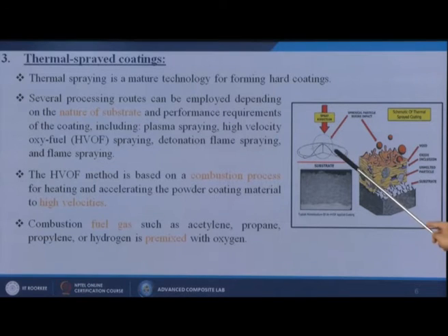Here we have the substrate, and we simply spray onto that substrate. This is the FESEM image where you can see the substrate in white color, and then a little bit grayish color showing how much coating thickness we have achieved by this thermal spray processing. Here also it is the same thing, this is our substrate.